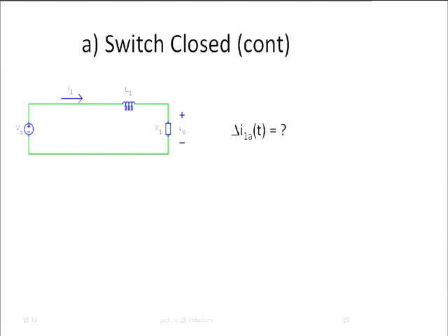We want, this is 110 volts, right? But if our circuit works all right, then this voltage here is going to be 10 volts. Your cell phone is not going to work if you give it 10 volts for a little bit, and then it's 0, and then it's 50, and whatnot. So if this circuit has any chance of being useful to operate your cell phone, the voltage here better be 10 volts always. Maybe it has a little bit of a ripple up and down, but not a whole lot, okay?